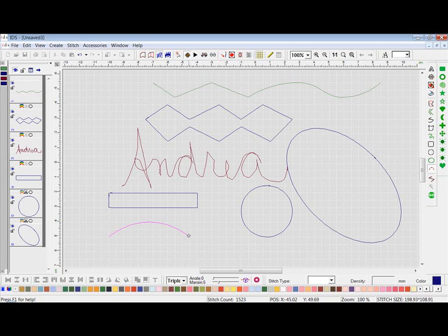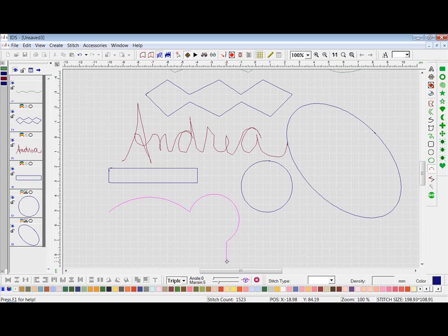Now, if we continue, since this is in a sense the end point of the first segment but the first point of the second segment, we'll make another left click, and that will be the center point, or the arcing point, and then left click again for the end point, and that will also act as the beginning of the next arc segment that we do.